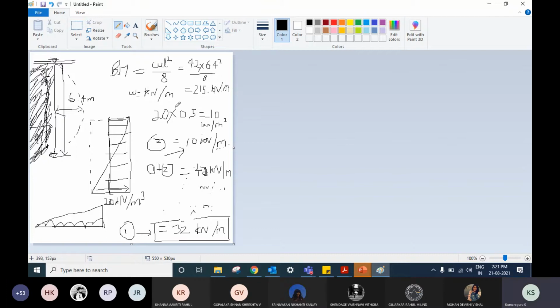Now let's remember, bending moment should be in terms of force into distance. So it should be Newton meter, Newton mm, or kilonewton meter. So from that you can always reverse calculate what you need to be putting in the formula. Now WL square would give you meter squared, and W should be in terms of kilonewton per meter. So meter in the denominator gets cancelled out, and you have a numerator 1 meter remaining. So kilonewton is already there, and this is a unitless number, 8. So we are getting the final units kilonewton meter. You can remember checkpoints like this always.